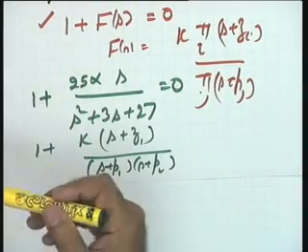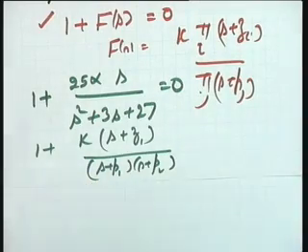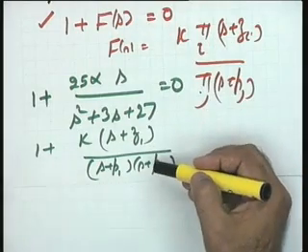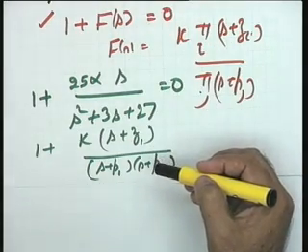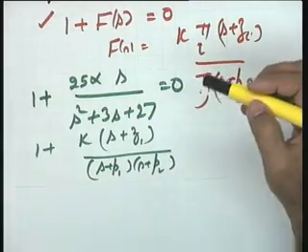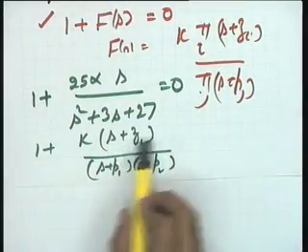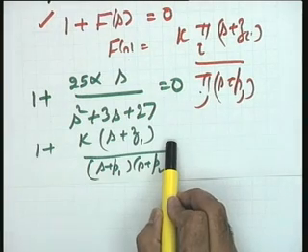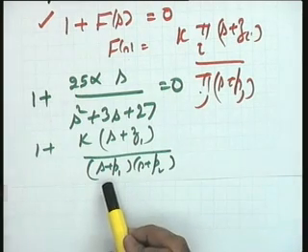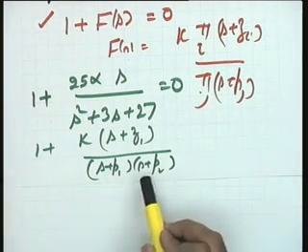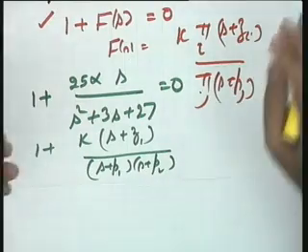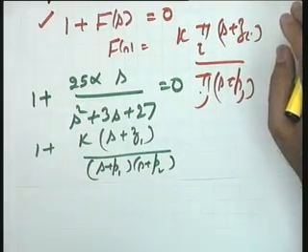So you see that in this particular case, I want to make it very clear that when I am taking F(s), the poles and zeros of F(s) are not necessarily the poles and zeros of the open loop system. Now the zero at s equal to minus z1, which is 0, that is at the origin, and the two poles at s equal to minus p1 and at s equal to minus p2 have no interpretation in terms of the open loop poles and zeros of the system under consideration.